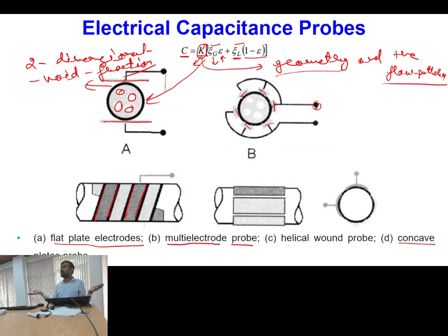So typically in a capacitance, depending upon the dielectric strength, you get the output. Whatever your overall capacitance is, that depends upon the void fraction. So this is the rule: dielectric constant into corresponding void fraction. Depending upon this mixture rule, you will be getting the output. Whatever distribution you have, you are not concerned. Ultimately, it will be giving you the simple value of the void fraction.